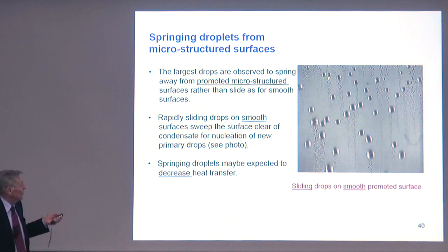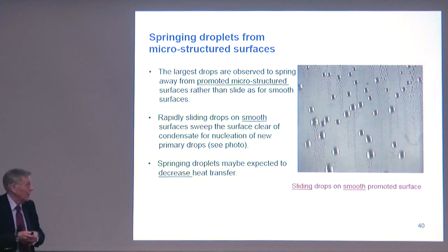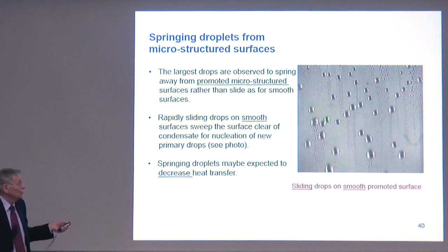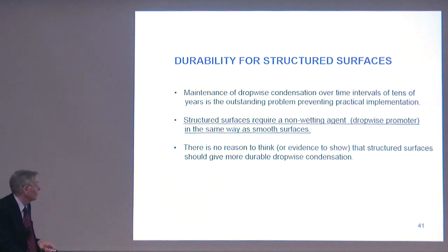But if these droplets spring away, you don't get this cleaning effect. These falling droplets, as I said, very, very fast, are sweeping the surface clean for new nucleation, new condensation. So I would expect, if the droplets spring away, that will be a negative effect. You'll have worse heat transfer, not the reverse as claimed.